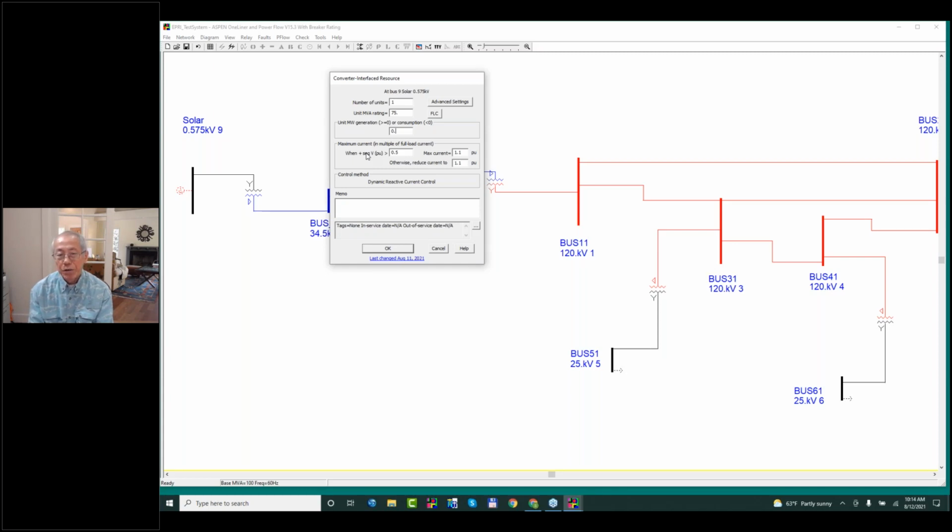In other words, you put a fault in front of that, and all of a sudden you get a very powerful transient of the energy discharged into the fault. So look for something that's at least about 1 cycle out, 1 to 2 cycles out. And generally, if you do that, you will see that the number is somewhere between 1.2 and 2, or maybe even 2.5. Most commonly, they're between 1.2 and 1.6. That's the number that I see most often in data sheets.